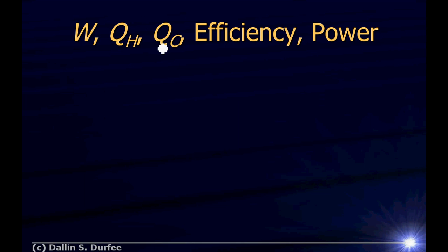But you can calculate them just by saying, here's when heat flows in. I take all the places where heat flows in, that's Q hot. Take all the places where heat flows out, that's Q cold. And again, efficiency is just work divided by Q hot, all right? And remember that work is Q hot minus Q cold. So if you could calculate just Q hot, work was easy to find, then it's easy to get Q cold and whatnot, all right? What is power?